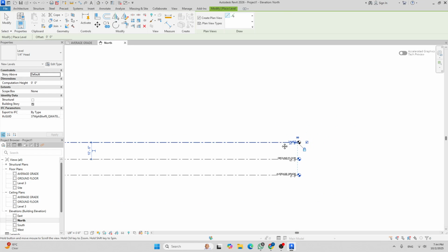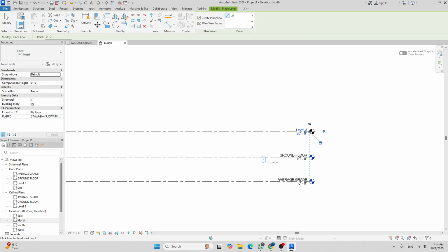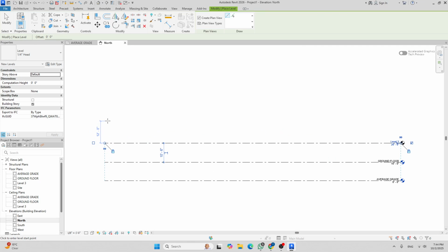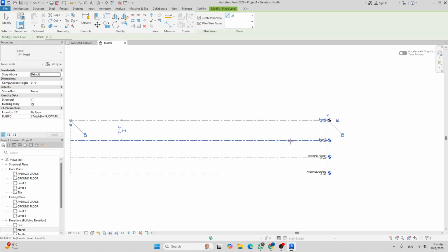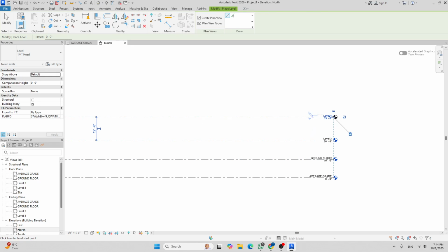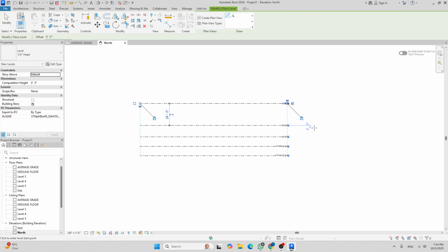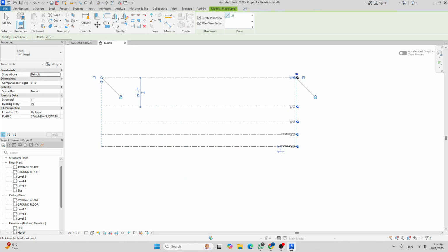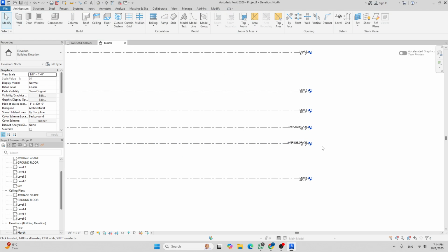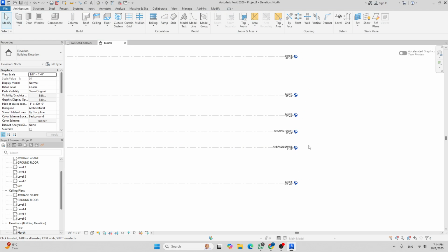It doesn't matter what the distance is between the ground floor and the next level. I'm gonna change the distance between them later, but we need a ground floor, a second floor, probably a ground floor ceiling and a second floor. Ground floor, ground ceiling, second floor, and I'm gonna create a new one for the second floor ceiling. And after that, probably I'll create one for the basement. So from left to right, click, and escape 2 times to escape out of the command.